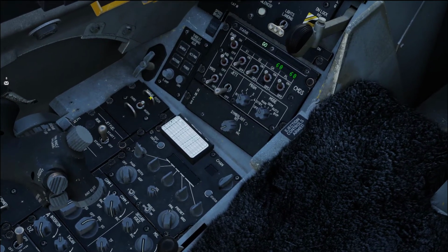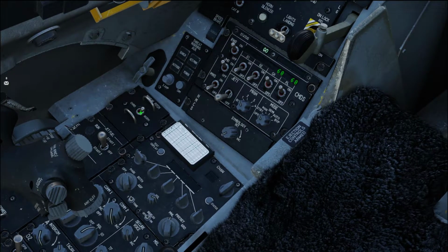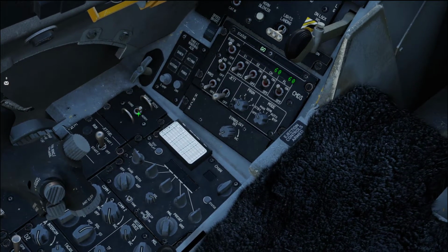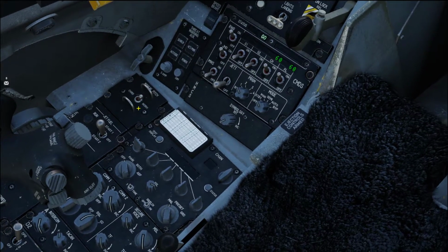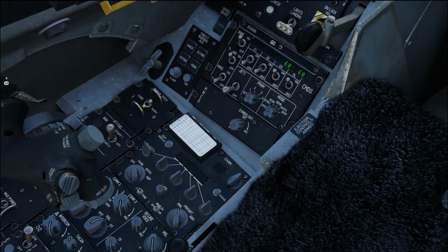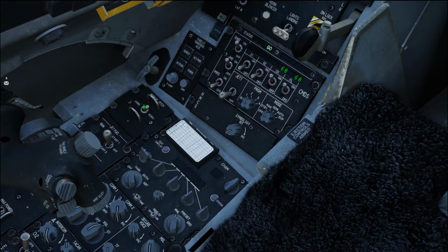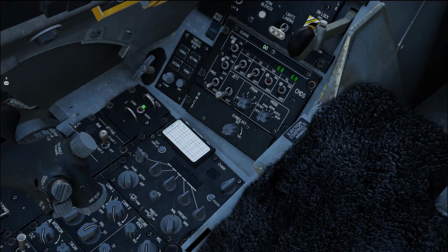This switch is spring-loaded to the normal position and can be held at the override. The override position is used in case of any deep stall or uncontrolled flight situation when the automatic recovery is unsuccessful. This disengages the pitch limiter of the aircraft and provides additional pitch authority for manual recovery.